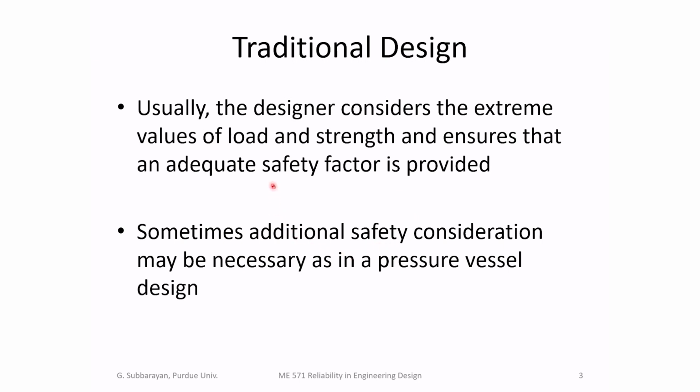So this safety factor accounts for all of our uncertainty associated with the design. And again, if you recall from our earlier discussion, the uncertainty comes about because of uncertainty in geometry or load history or material behavior. So we'll lump all of that into one safety factor.